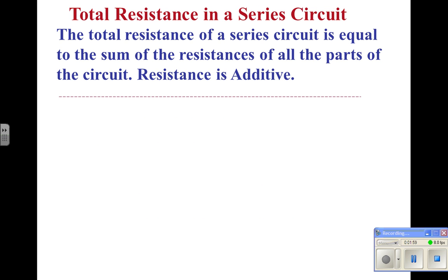Okay, the resistance in a series circuit is additive also. So series circuits are the most simple because most everything is additive, and then current's constant. And so that means that the resistance of resistor 1 plus the resistance of resistor 2 plus the resistance of resistor 3 is the total circuit resistance. It just adds up. No big deal. Okay.